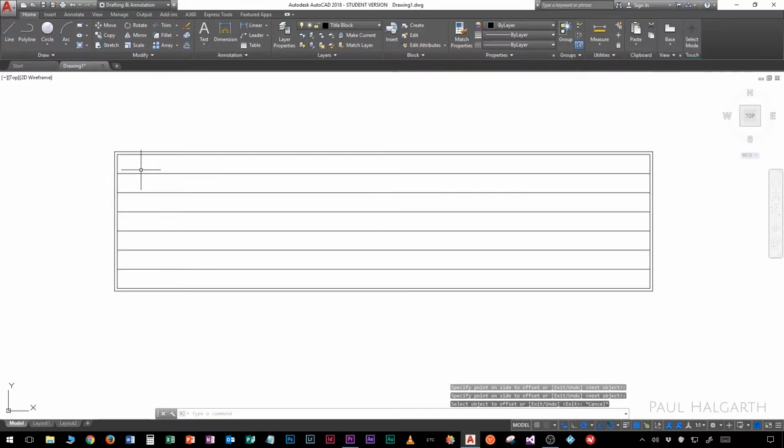Okay, that's great. Now we need some vertical lines, so we're going to pick up the line tool and we're going to hover over the bottom right hand corner on the inside border, and I can see the first one is 212 in. So we type in 212, press enter. That's now drawing 212 away from where we started, and I can see that goes up the first two rows from the bottom.